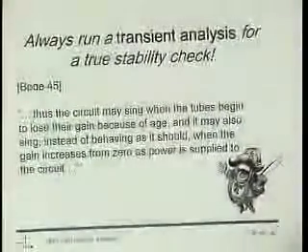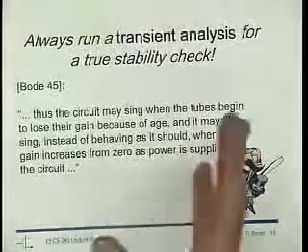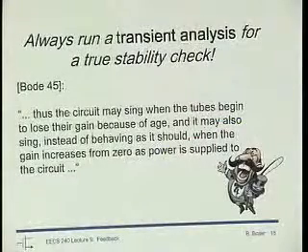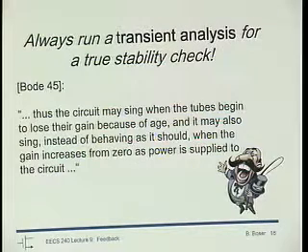So we still need a crutch, and so once we have verified that at least our circuit sort of is in the right place and operates the way we think it should, then it's still going to get there, right? If you're sending out a chip to the fab, I promise, you were going to run one analysis, a transient analysis, where your input is VDD.